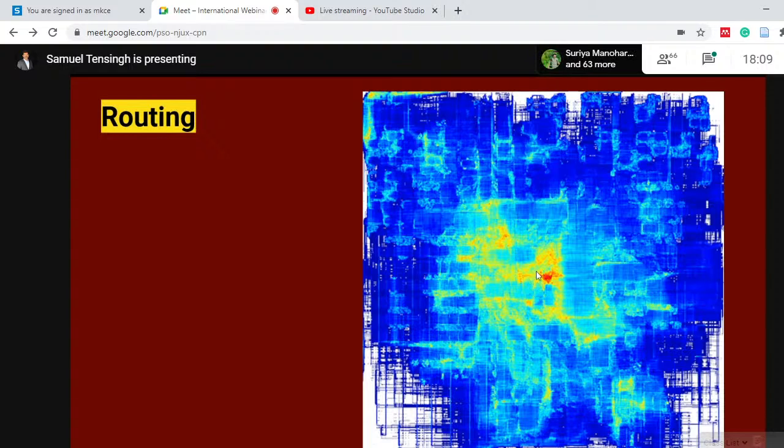Once you see this, you need to go into your database and see why this area is congested. Are there any timing nets, like long nets here, or any loops of nets in this location, or is there any standard cell creating congestion? You need to understand and see why. If you have more congestion in this area, subsequently when you do DRC analysis, you will have more shorts and spacing violations in this area. So if you fix it during the route step, then it is easy for you when you do the physical verification process.